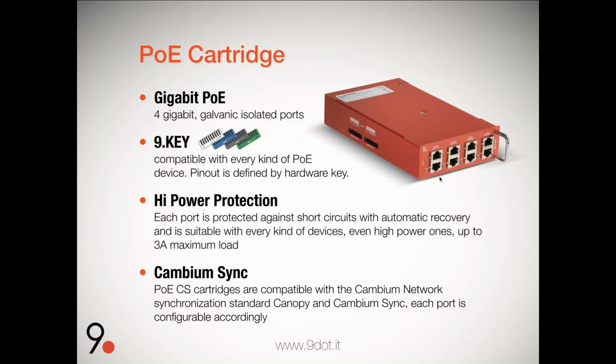Each slot is for a 9-dot key. The 9-dot key is a little key that lets you decide the pinout of the PoE. So if you need to power a Mode A PoE device, just plug in the right key. If you need to power a Cambium device, just plug in the right key. If you need to power, I don't know, MikroTik passive PoE devices, just plug in the right key, and you have the right pinout on the port, and you can change it whenever you want.